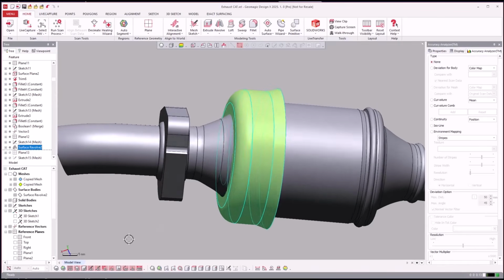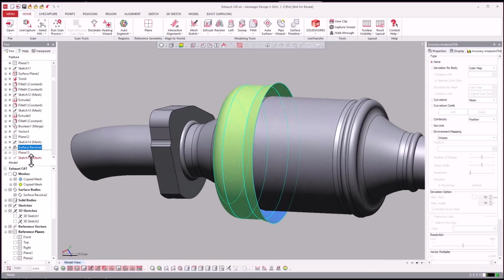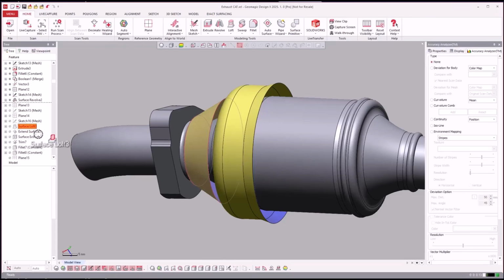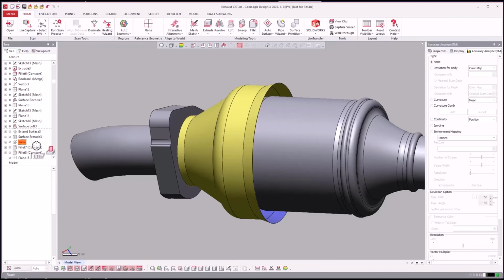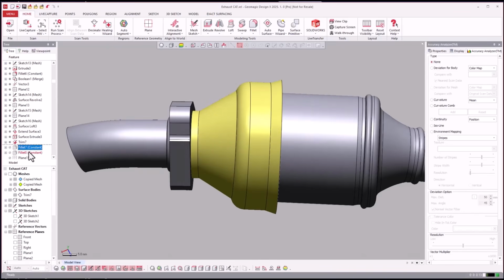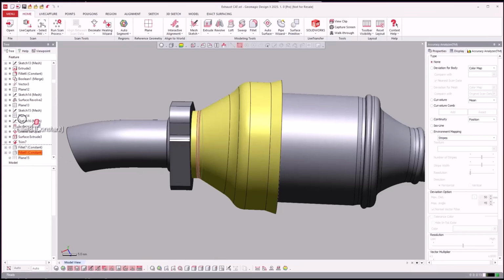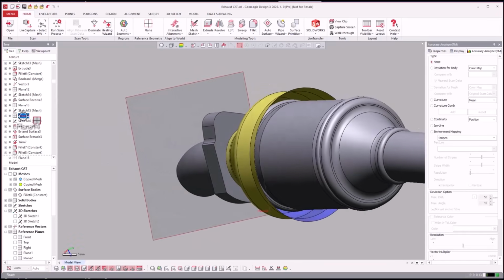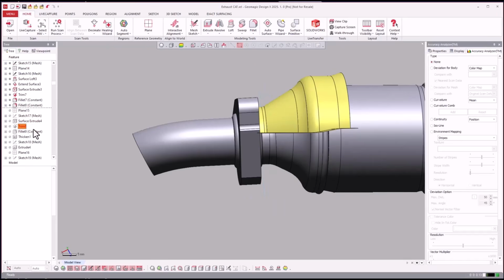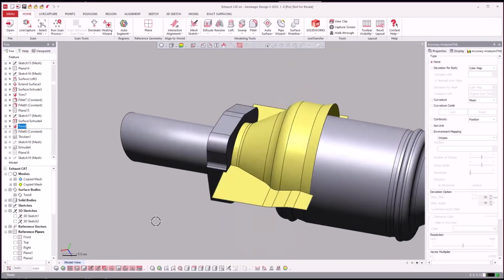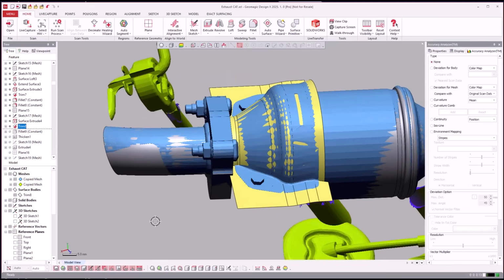Okay, so now we are going to go ahead and revolve the heat shield, do a surface loft about that, do a surface extrude and trim it all together. There we go there, fillet that, really neat. Then we're going to go ahead and trim it in half. We'll just turn on the mesh so we can see.